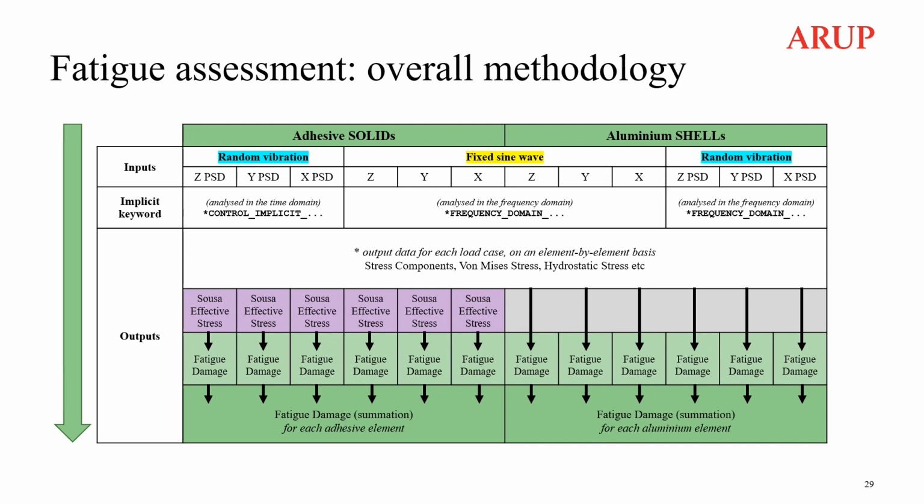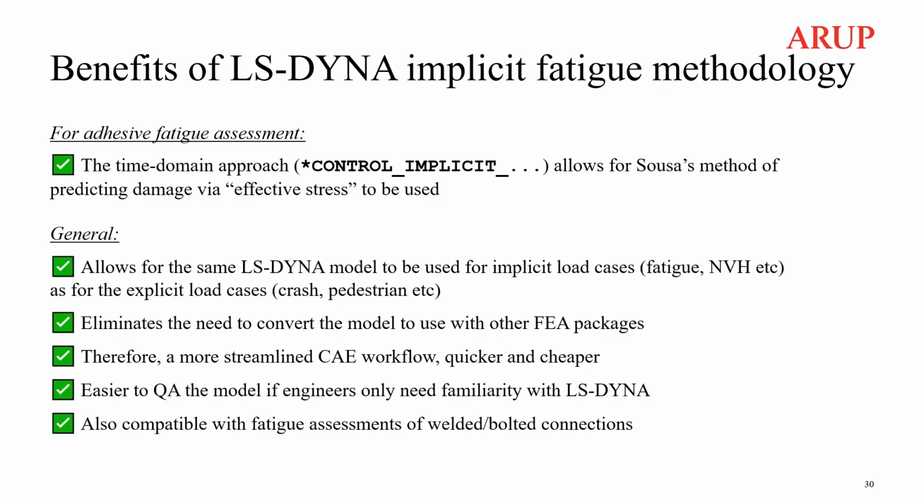frequency domain approach. Now I will highlight the key benefits of using this LS-DYNA implicit methodology for fatigue assessment of structures. Specifically when assessing adhesive, the time domain approach allows for Sousa's method of predicting damage via effective stress to be used. In general, this methodology allows for the same LS-DYNA model to be used for implicit load cases, fatigue, NVH, as for the explicit load cases, crash, pedestrian, eliminating the need to convert the explicit LS-DYNA model to use with other FEA packages.